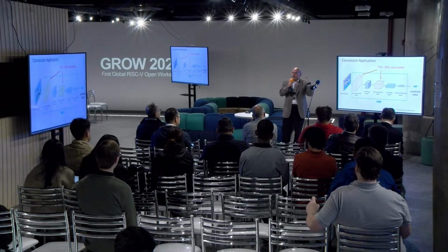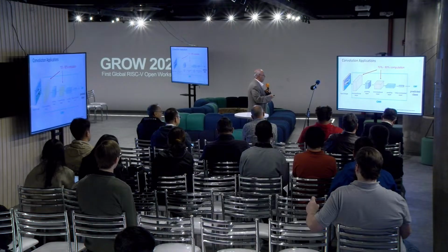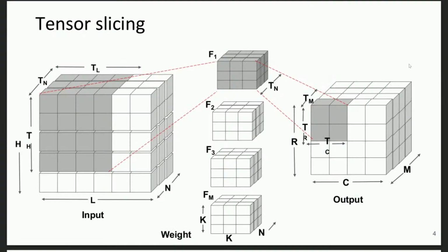So that's a very important issue if we're going to do slicing for AI. So what is the problem? You have the filters or weights, and you have this input tensor here, which is larger. What you want to do is slice it and touch each slice once: it goes up the hierarchy, stays there, and is never touched again. It's pretty much standard stuff. So you slice this larger tensor, do the convolution, and produce an output block.